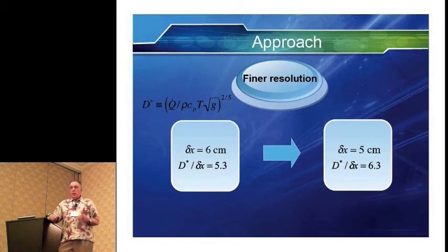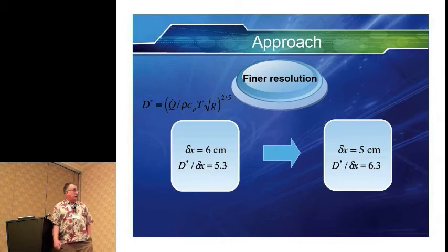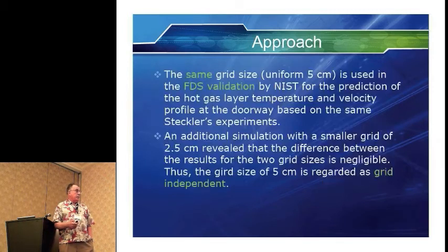They also corrected a little bit for radiation. I think they initially used the default value for radiation fraction. Then they went back: hey, this is a methane burner, we should probably use a lower fraction. They put that in and then ran it. So this is the finer resolution, and that's what they chose. Let's see what this says.